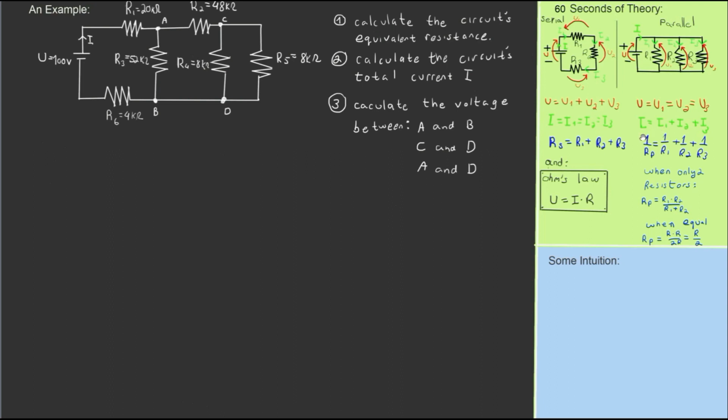And when you look at the equivalent resistance, that's the theoretical formula, but it's not the one that you typically use, because there's a simpler derivative of this formula for two resistors, which is this formula down here, and an even simpler one when there are two equal resistors in parallel. You simply get an equivalent resistance that's equal to half of each of the resistances.